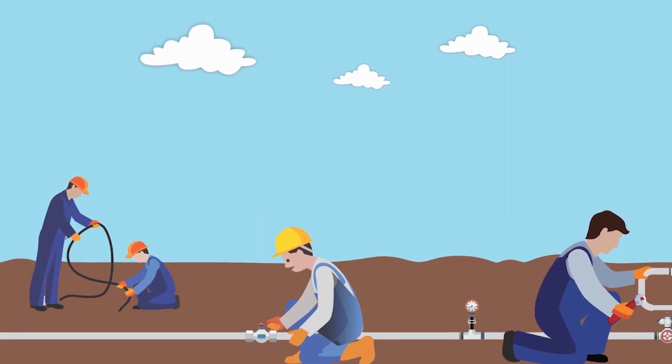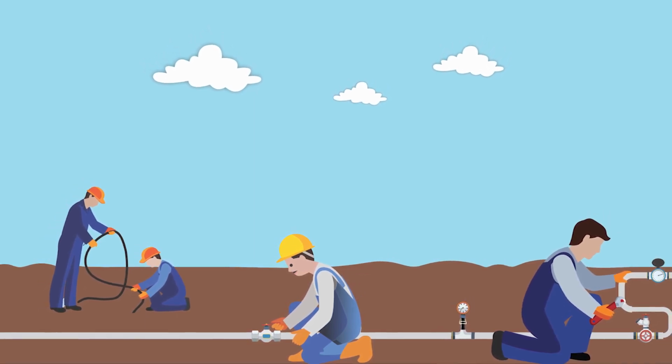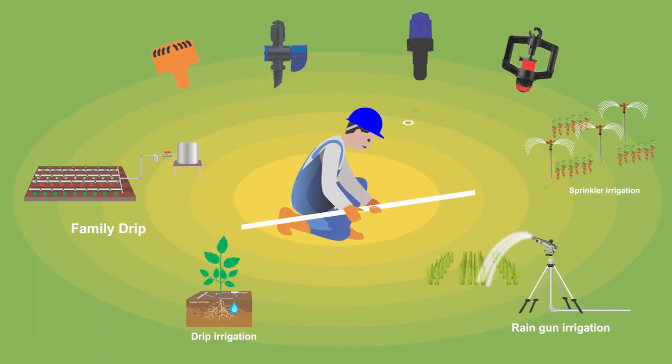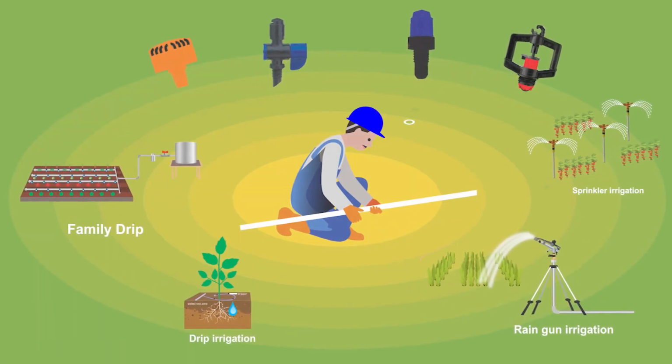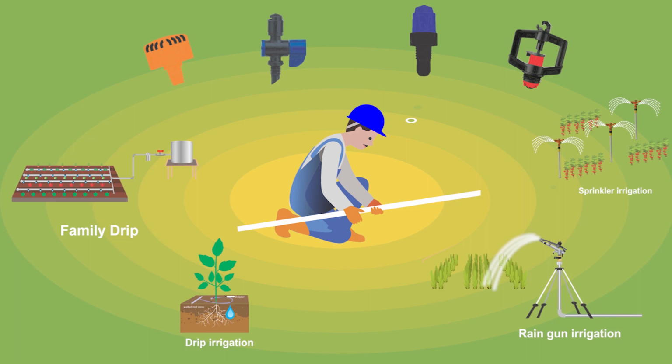Proper and timely maintenance of micro irrigation system is necessary to ensure most efficient use of water that is being applied. The micro irrigation system should be cleaned and maintained periodically to remove dirt and debris that have built up over time. Replacement of irrigation system components must be made with materials of the same manufacturer and model as the original equipment. All parts must have the same output and coverage specifications as the previous equipment and components of the micro irrigation system. Now, the maintenance can be done daily, monthly, weekly or yearly.